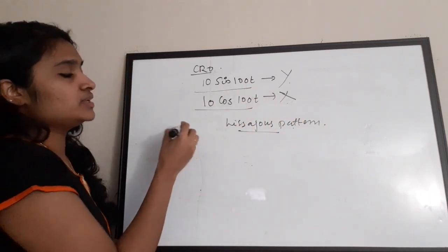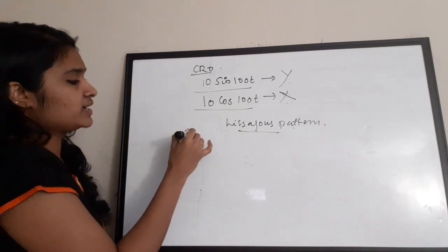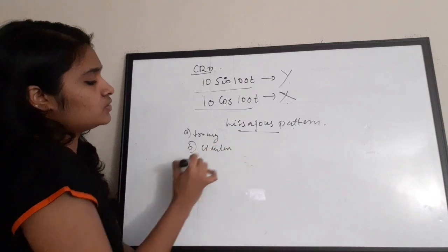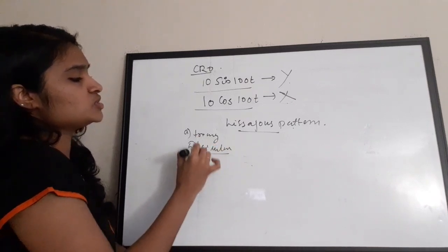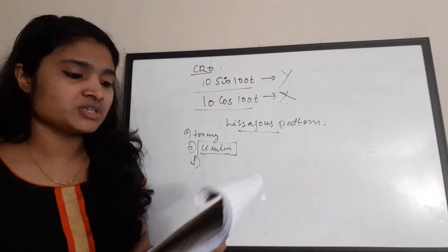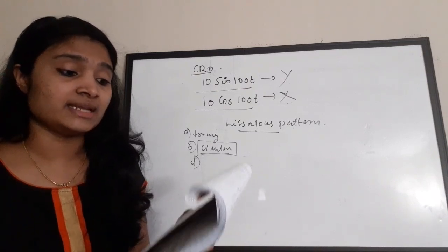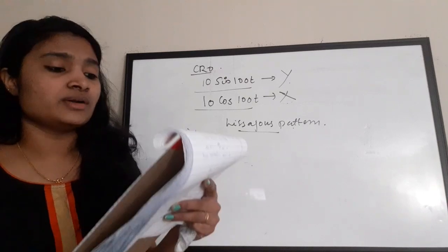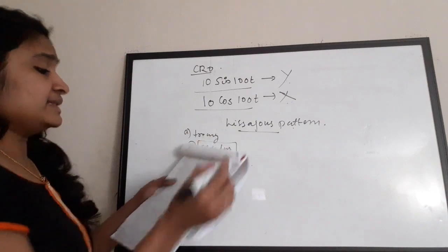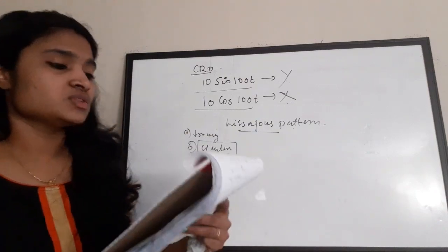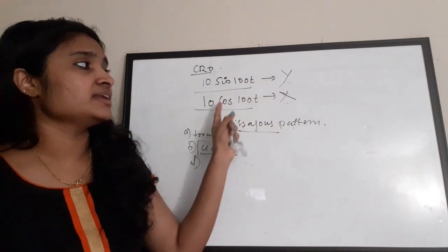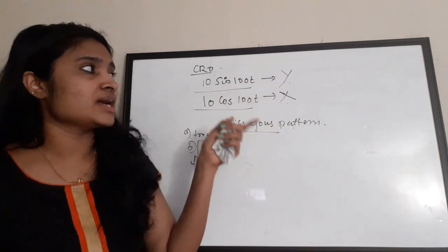If the options are given as A triangular wave, B circular wave, or C square wave, you have to choose the circular pattern. If the options are A a sinusoidal signal, B a straight line, C an ellipse or D a circle, you have to choose a circle. It is actually called a Lissajous pattern. The Lissajous pattern is obtained if X and Y are fed with a sine and a cos wave with both channels having same gain.